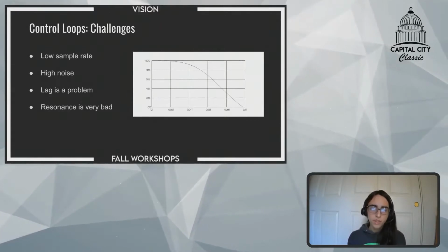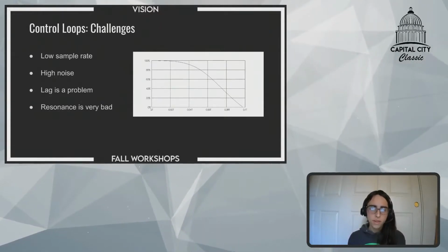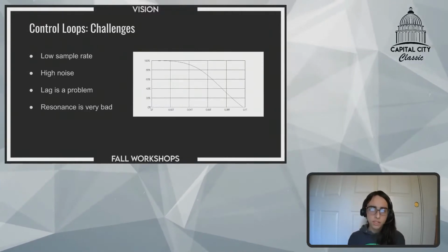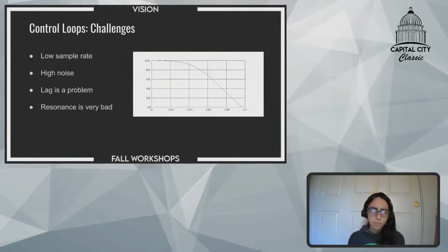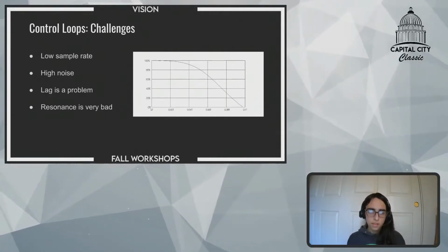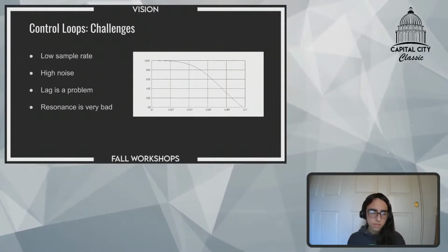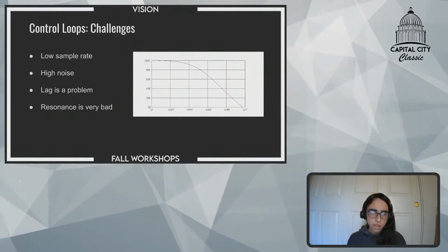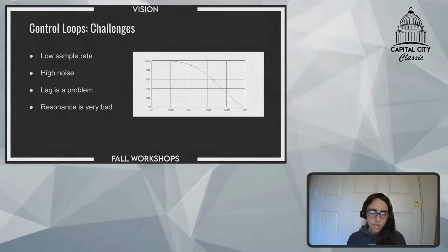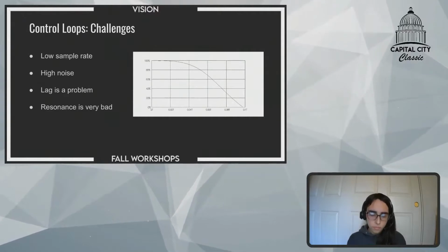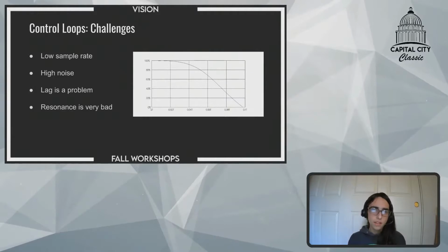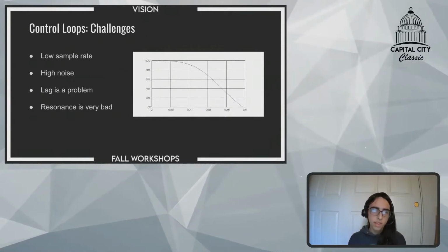One thing that doesn't get mentioned enough when discussing how to implement a computer vision system is what to do once you actually get that position data. There's a temptation to say, okay, we have a decent frame rate, we can use this as just another sensor, use it for feedback on our PID loops, but that doesn't work very well. There are a few differences that make a camera meaningfully different from other sensors. It has a higher noise, it has a lower sample rate, and higher latency.